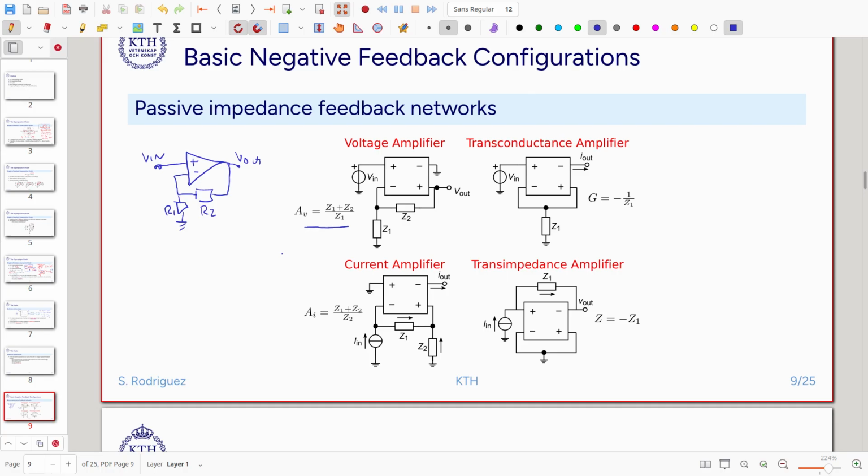Then the properties here. Amplification here is infinite. All the ABCD parameters are 0, so there is infinite amplification. When there is infinite amplification, some interesting situations arise. Another property is that no current enters the nullor.